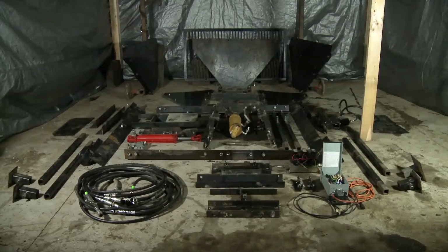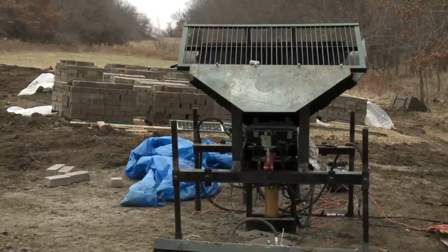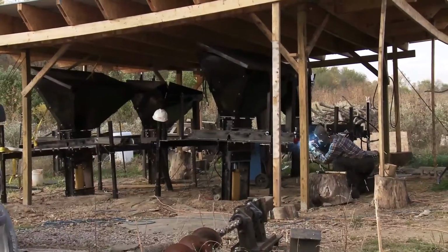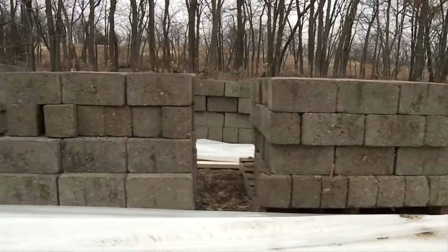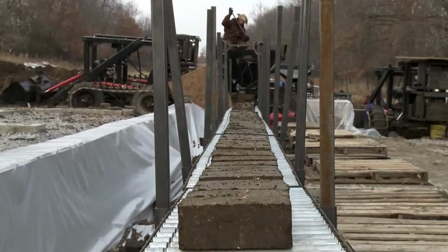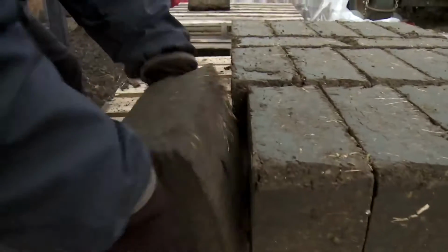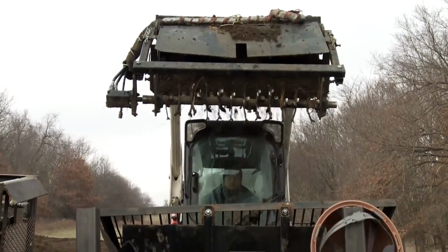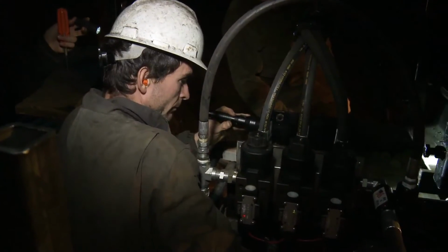Compressed earth brick presses. We called it the Liberator, as in liberating you from the main cost in your life, which is housing. If you have one of these machines, you can make bricks, which in principle can suffice to build an entire house, including roofing and flooring. Compressed earth brick, to my knowledge, is the only technique that's rapid construction, requires minimal equipment, and can get you both natural and industrial scale building. It's driven by hydraulic power from a power cube, so you can stand a power cube alone.